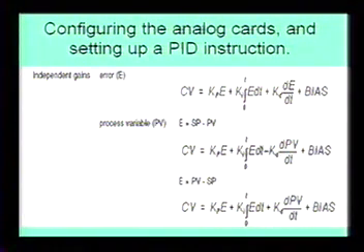Increase. And it would increase, and more chemicals would be dumped into the solution. Then finally, 20 minutes later, it'd say, hey, wait a second, you've got too much chemicals. So the controller would say, okay, I'm going to come all the way down to 0. So this thing would go on, then off, on, then off. So the loop update time and the entire process need to be fully understood before you implement one of these PID instructions.